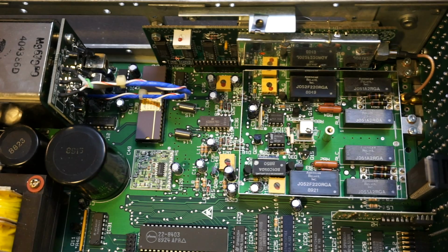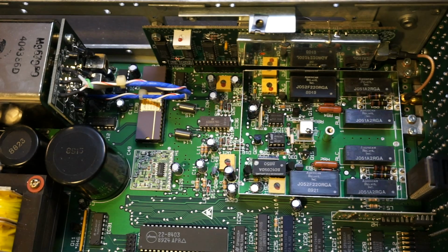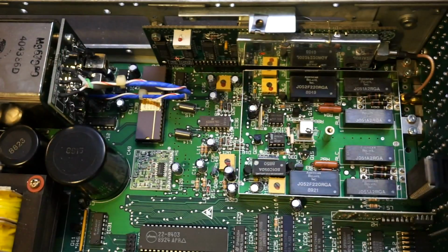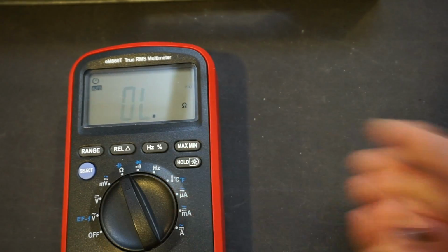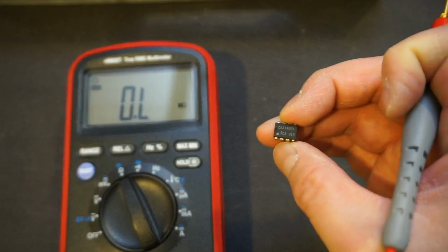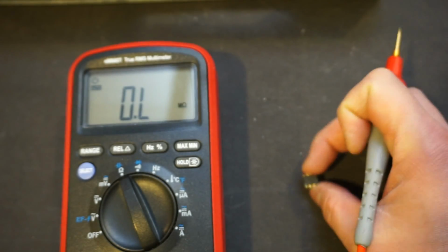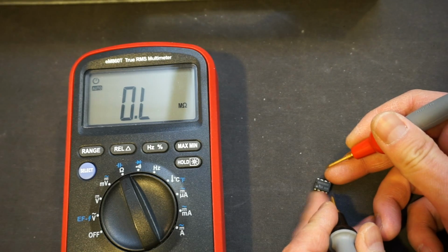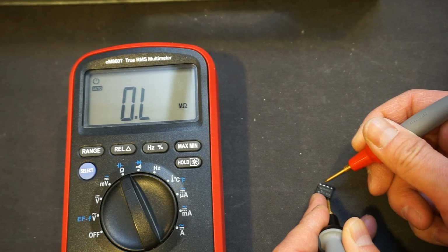So after I took out the IC originally there, I can confirm that it was definitely shorted. So I can show you here. Let me first move this away, and let's turn this on. Let's turn it to the ohm range. So here is the CA3140 that I took off from the frequency counter from channel A. And if I measure pin 4 and pin 7, so these are the VCC and the VEE, the two rails,